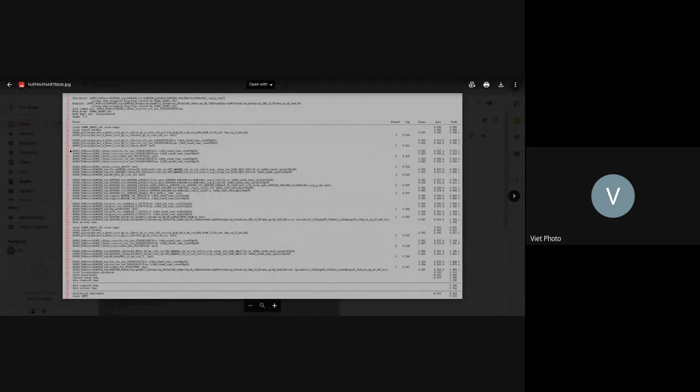Now the next one here, you have a 3 dot here. It means I have quite a few cells here, but I just cut it short so we don't get confused with that. So this one you have the A to NZ, right? So A here at the beginning you have a 7 picosecond here. So this one is the wire delay. The number that appears at the A means a wire delay. What appears at NZ is the cell delay, because the delay at the end of the input is a wire delay, and the delay at the end of the output is a cell delay. So keep going like that.